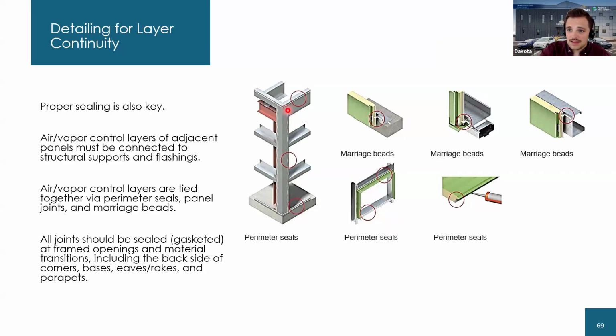Essentially, and you'll see it here glued all over that structure, it's like a silicone that never quite gets dry. Unlike the caulking you use around your bathtub that eventually peels up, this stuff stays wet for the duration of the building, meaning that it can allow for a little bit of movement and still keep that air sealant nice and tight.